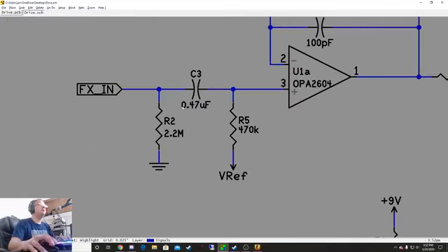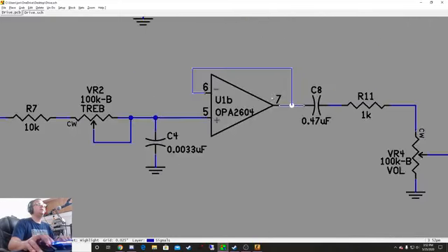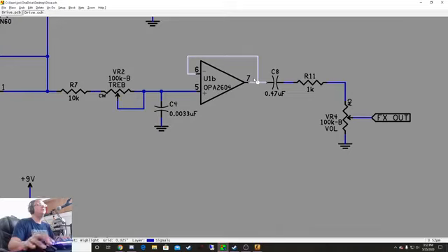For instance, over here, I want these parts close together and as close as possible to the op amp. Obviously, layout has a lot of things where you have to do things you don't necessarily want just because of physically where parts are. But this one I don't really care that much about. I care more about the stuff that's feeding this.